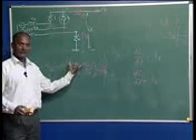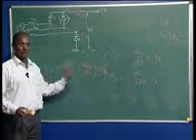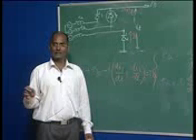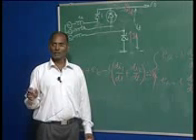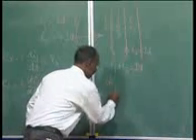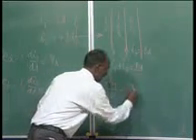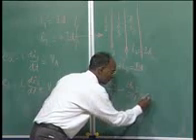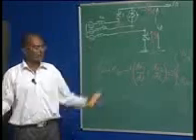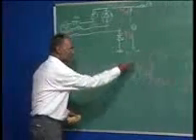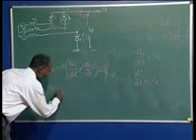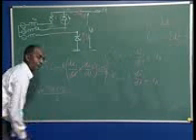We know in this condition, I1 plus I3 is your ID, the DC current, and it is assumed that the DC current is constant, and once you differentiate it, it will be 0. Means simply you can differentiate it here, you are going to get di1 over dt plus di3 over dt equal to 0, because the DC current is DC, and if you differentiate it with time, it will be 0. So, what happens? This is 0. Now, you can say here VA will be your EA plus EB by 2 all the time.